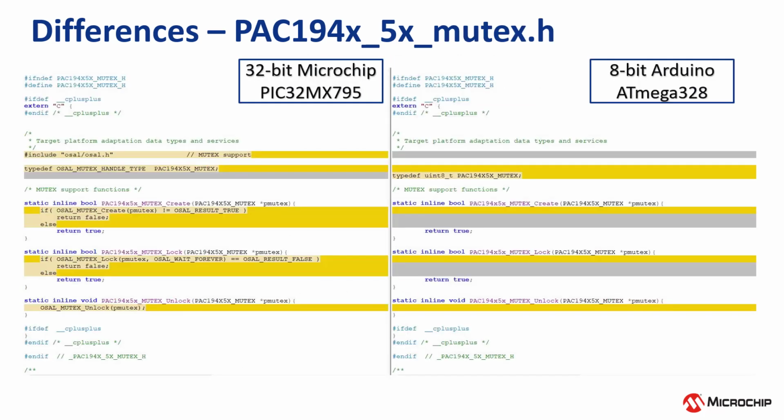The Arduino platform uses the library in blocking mode because the platform's I2C driver does not offer support for simultaneous transfer requests with multiple clients, and the mutex functions become empty functions. There is no need for access synchronization because the application is single-threaded and the library works in blocking mode.